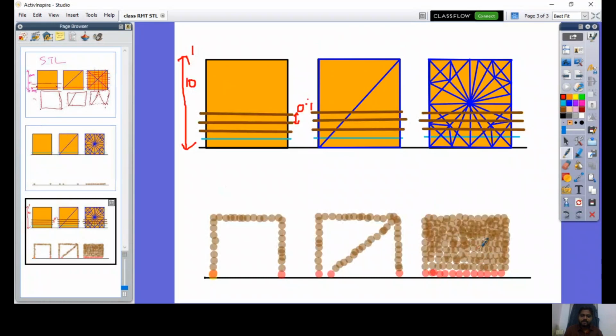So this will be repeated layer by layer, because you are going to slice into n number of layers. You are going to divide a CAD model into n number of slices. Each slice will have an intersection point with the edge as well as the STL edge you have created, and all those data will be transferred to the machine. Then that data will be used by the machine for material deposition or material joining. Finally, you get a three-dimensional model.